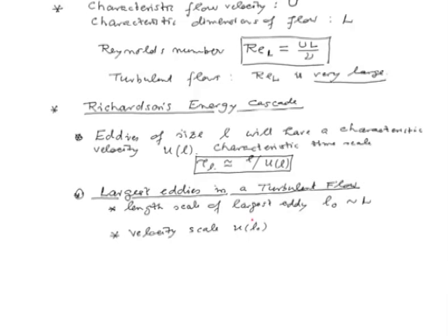The flow velocity can be decomposed, and later on we are going to formally define that Reynolds decomposition, as an average component and a fluctuating component. This fluctuating part is the one which is a feature of the turbulent flow, and we can get its root mean square value. So, the velocity scale of these eddies, U of L0, is identified as the RMS of velocity fluctuations.